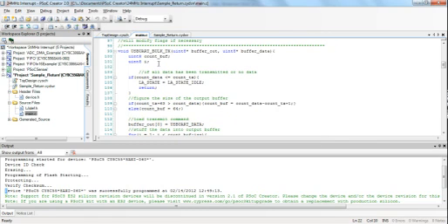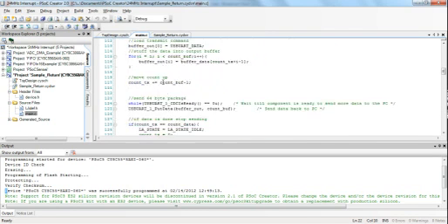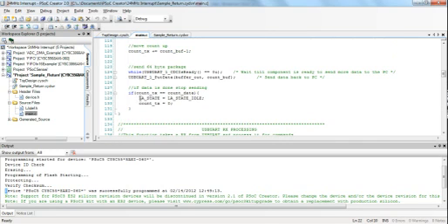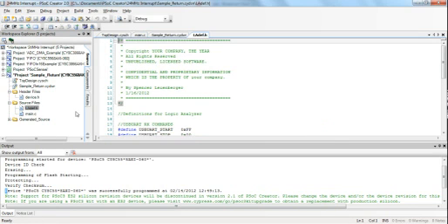What it does is it goes through the 1,000-byte sequential buffer and breaks it up into 64 or however many I want, until the end of time, and keeps sending data. And once it's done sending data, it changes the logic analyzer state to idle. Actually, let's go look at those.